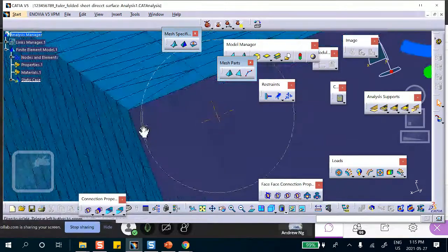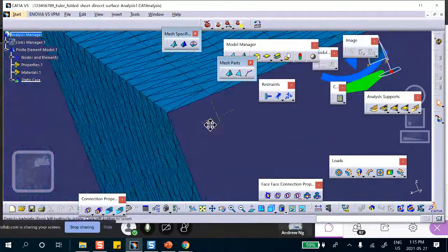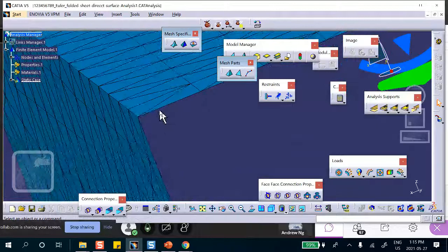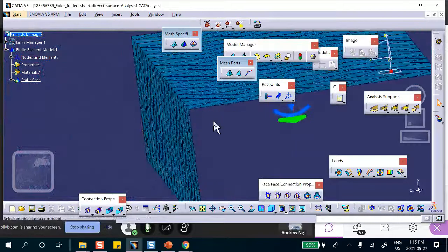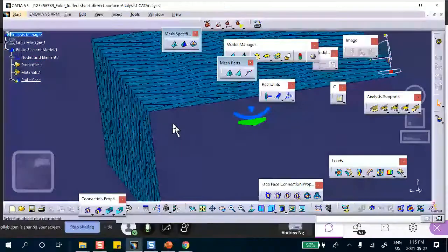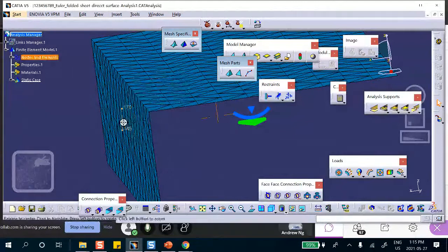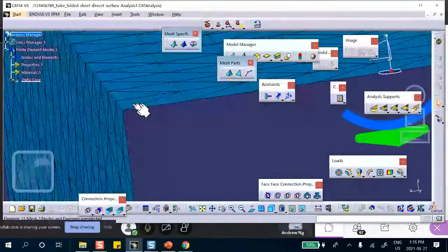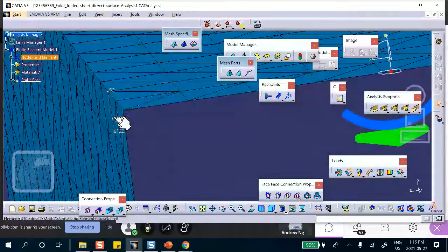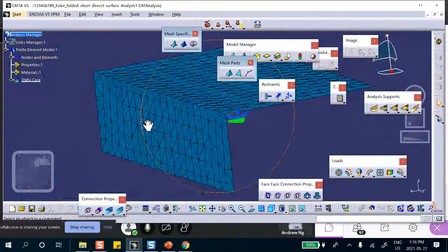Now, the way it's done in the book, if you don't join the nodes on this side and the nodes on that side, they're going to have different node numbers, and then you have to do some other stuff. But if you join it, that won't happen, because it's a single surface that you mesh, basically. Here, I didn't have to join, but I said, if in doubt, join it, and it's going to be the same thing. Okay. All right.